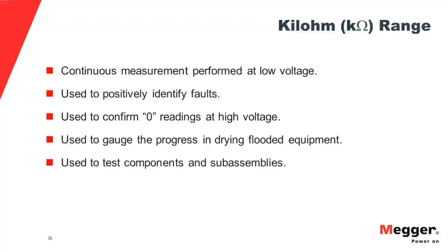And the kiloohm range now, again, this is a range that's intermediate between your continuity and your megohms. Here you're measuring in thousands of ohms. And again, this is done at low voltage, usually maybe 3 volts or something thereabouts. And it has some very vital functions. Not all testers have a kiloohm range, but in many cases you want to make sure that you get this.